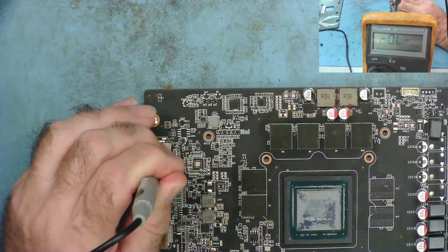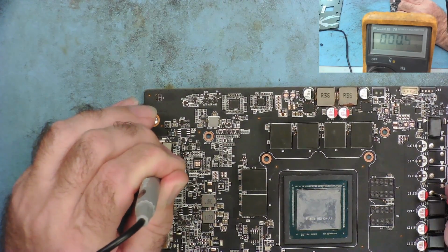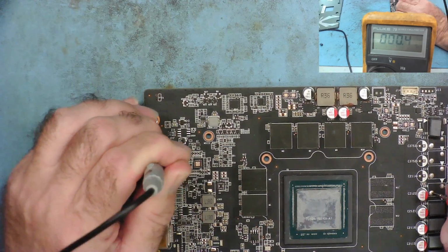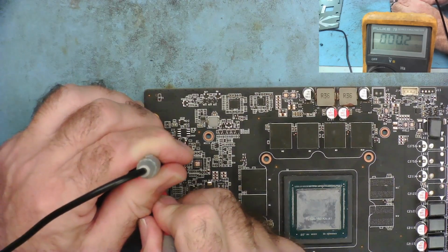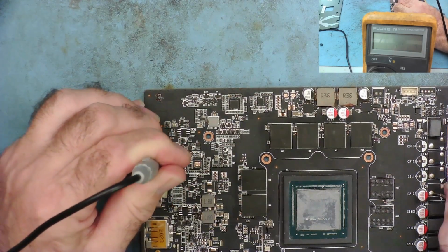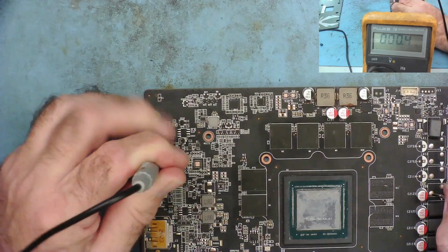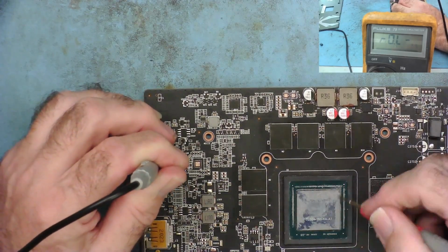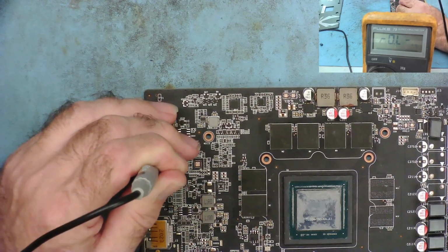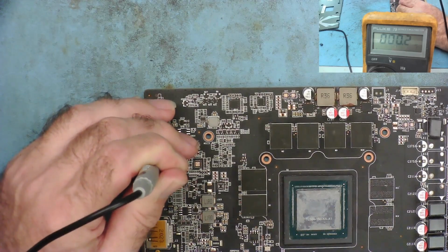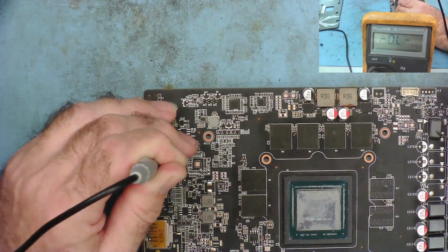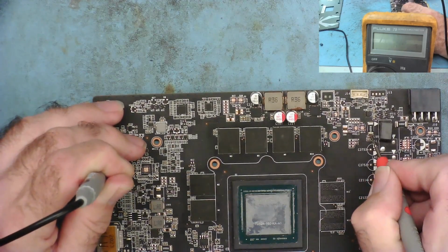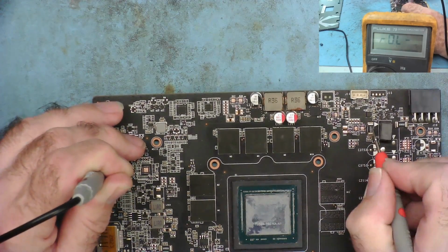That looks okay. What's the V core reading? That'll be these. Well, it's reading very low, but this is likely to read very low anyway. See, 0.2 with them shorted and 0.4 with them not shorted, so that doesn't surprise me. That's probably okay. So what we seem to have here is a short circuit on the 12 volts coming in from here, through this current sense resistor, through this. Is this connected to it as well? Yeah, it's there as well.